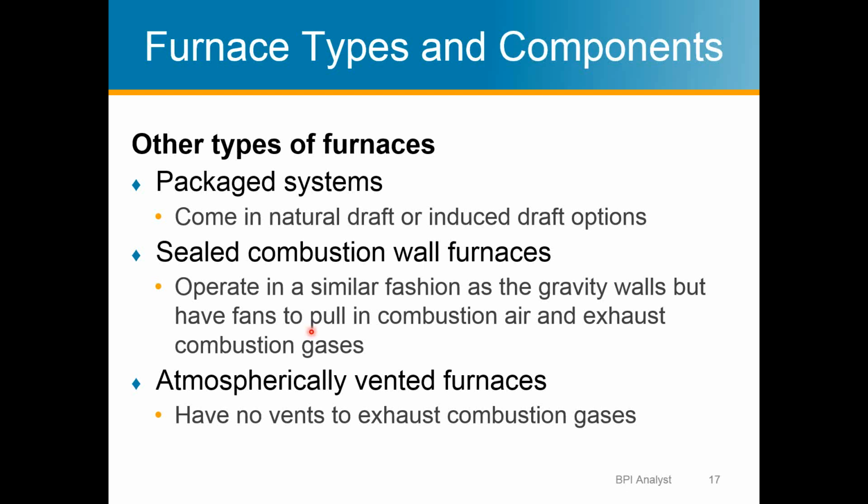There are some sealed combustion wall furnaces. They operate similar to the gravity wall furnaces, but they do have fans that help pull combustion air in and exhaust them. And then there's atmospherically vented furnaces where all the exhaust gases go straight into the living space. That's probably illegal in most states. I know it is in California, but they do exist.